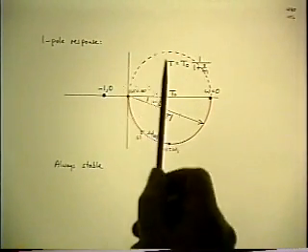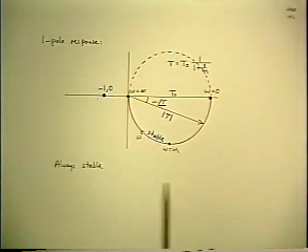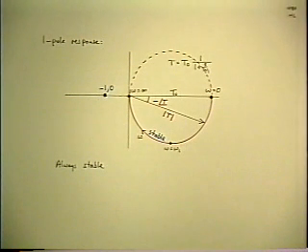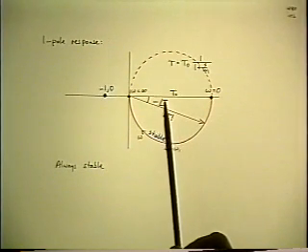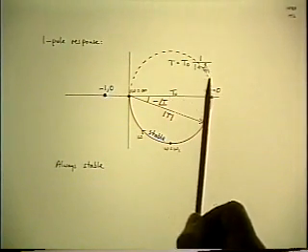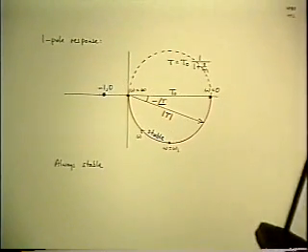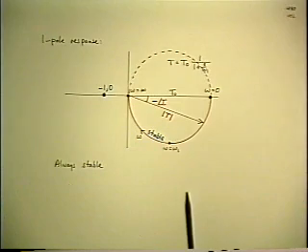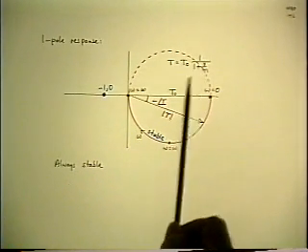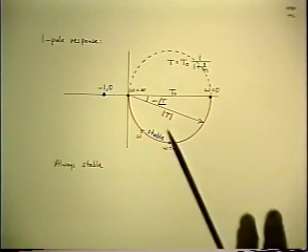So the Nyquist criterion says that the closed contour must not encircle the -1 point. And so when you look at this result, the answer is it does not encircle the -1 point, and moreover, it never will, regardless of the values of the parameters. Because changing t0 or omega 1 simply changes the scale of the circle, but it will always remain on the right-hand side of the origin, and it will never get to -1. So the conclusion is a single pole loop gain is always stable. So that's the base comparison position.